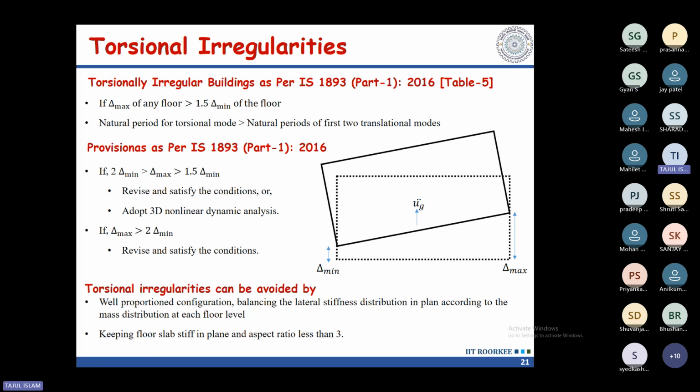Yes. So you analyze the structure using linear time history analysis. As an outcome, what do you get? That is the forces, the force demand, what is expected during earthquake. That's what you get, right? Yes. So my question, in this case, why do we need time history analysis?